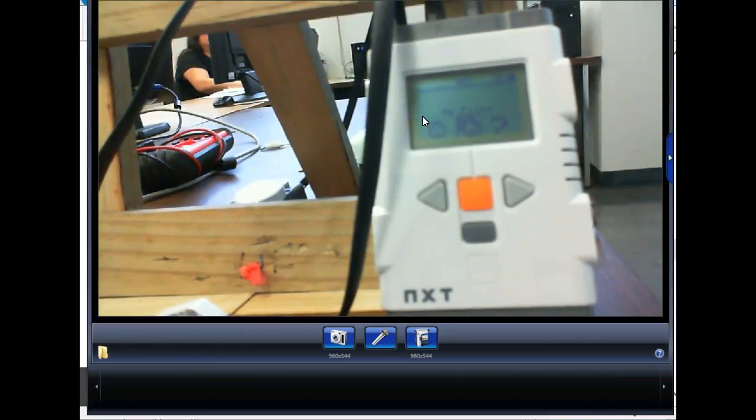But there's a limited amount of memory inside this controller, so the online teaching is very, very limited. Basically, we're going to use it while we're building the robot. We're going to use it to verify the steps of the assembly process. So when we add a sensor, we're going to do an online program that checks to see if that sensor is doing what it's supposed to do.